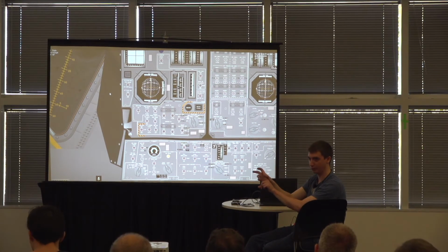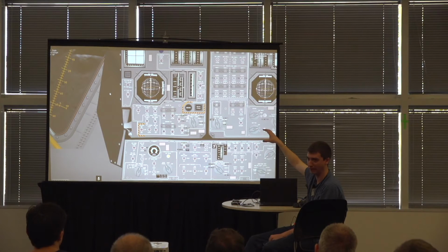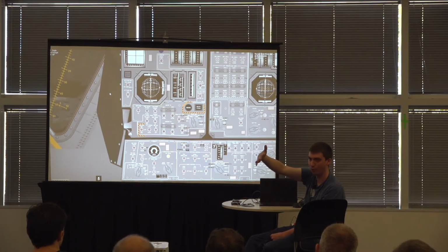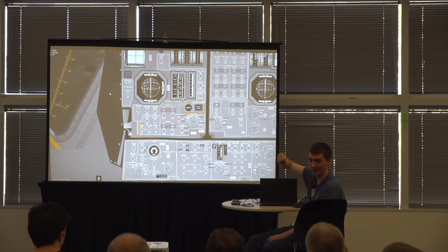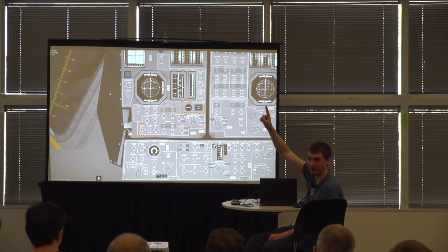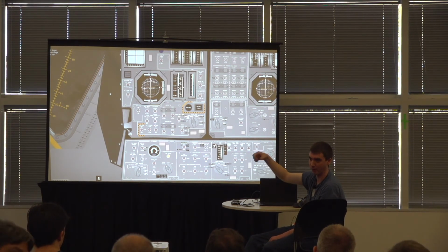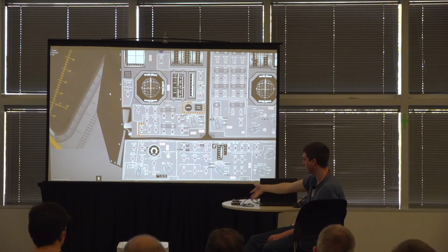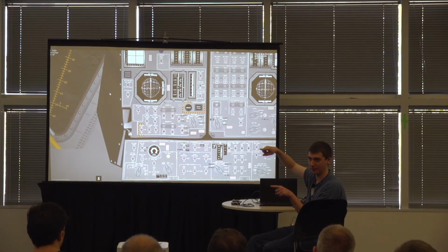And the difference in phase and voltage between what the analog to digital converter that the AGC was using and the reference voltage that was actually being put into the rendezvous radar made it think that the radar was seeking back and forth very quickly. And so it was generating a whole bunch of inputs to the AGC. And the way the AGC inputs work, it steals a cycle from the instructions to use the adder to add 1 or subtract 1 from the angle in hardware. And so this flood of +1 counts and -1 counts was stealing time away from the program that was executing. And essentially, it backed up on jobs to do.